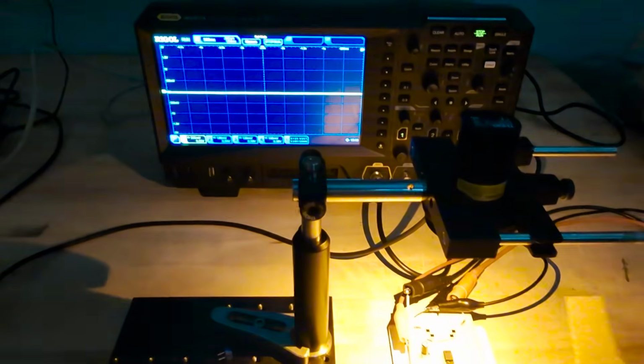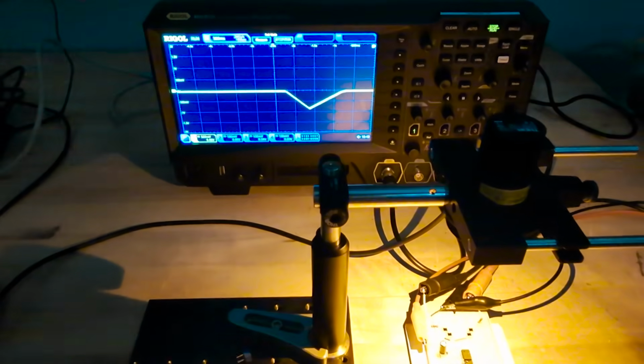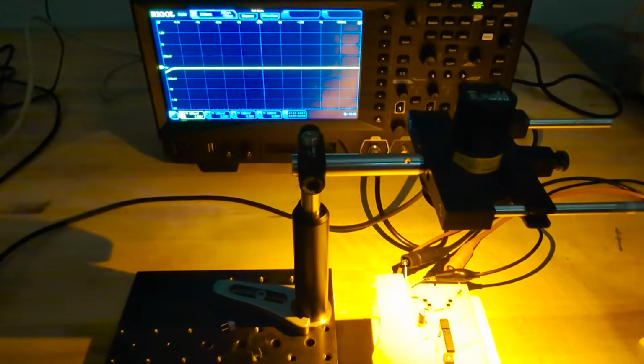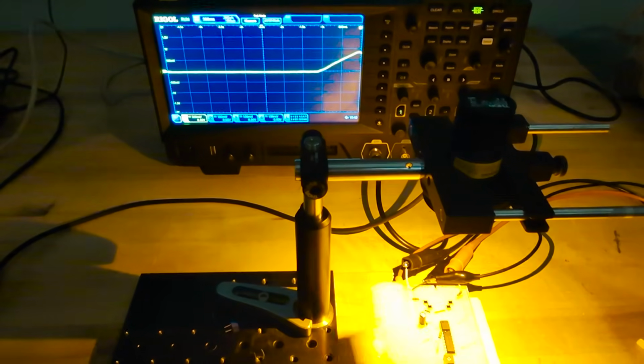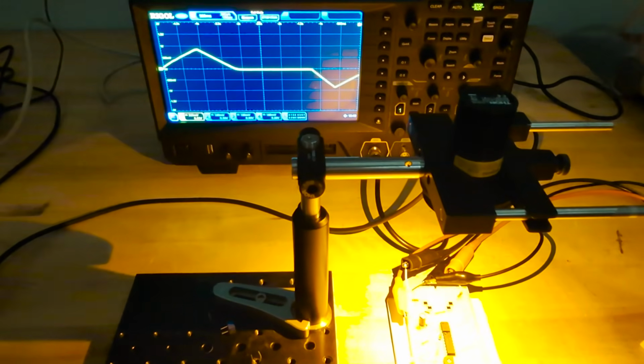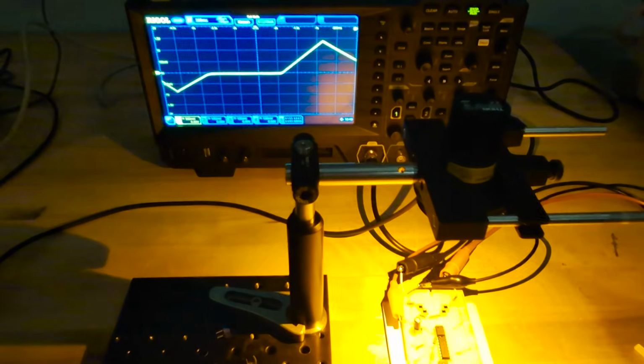So now what's going to happen? If we block the right group here, again, we see a rise, but now what happens? We see that it decays back to this baseline 0 much, much quicker. So now let's try covering the left one, and we see a similar behavior. So the circuit allows us to control the decay time by adjusting the trim pot resistance, which is nice.